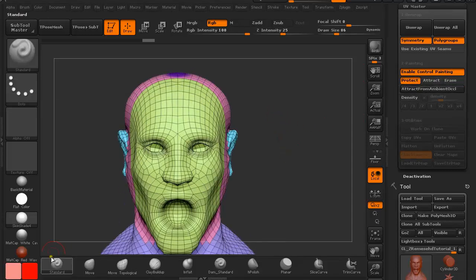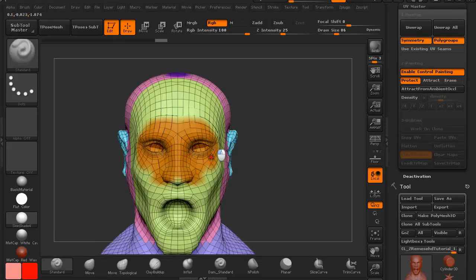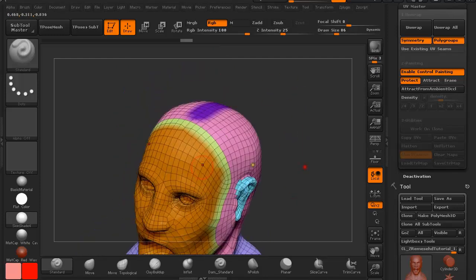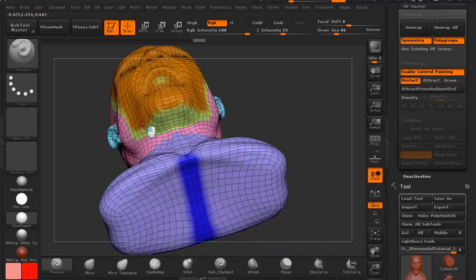So if you turn on protect, it's going to select the red color. We're going to brush the whole face so no seams are present in the face, which is really important when you want to animate something and you have a texture over it. If the seams are not placed accordingly, it's going to show in your texture distribution when you animate your model.